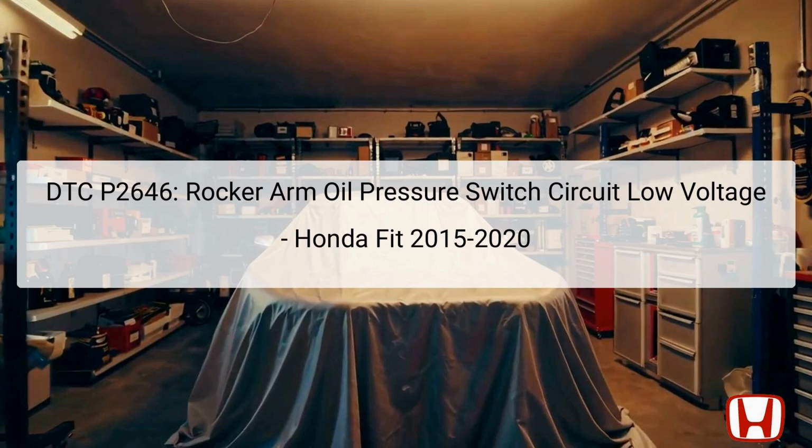The rocker arm oil pressure switch is primarily located near the engine block, and it monitors the oil pressure within the VTEC system. This code can inhibit the functionality of the VTEC system, which is crucial for optimal engine dynamics, particularly under varying speeds and loads. Furthermore, while diagnosing this issue, it's essential to be aware of other associated DTCs, such as P2648 and P2649, which should be resolved first if they are concurrently present.